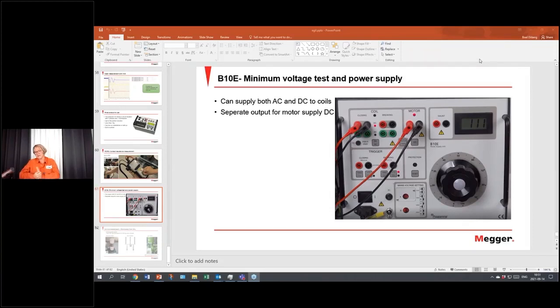But for things like this vacuum test, I would say if you move a circuit breaker, then you should do this kind of test, and when it's new. If there hasn't been any extreme situations, maybe you don't need to do the vacuum test every 5th year. But if you transport a circuit breaker, you can understand there could be mechanical damage to the pole, and that's important to find before you put it into service again, because it can explode.